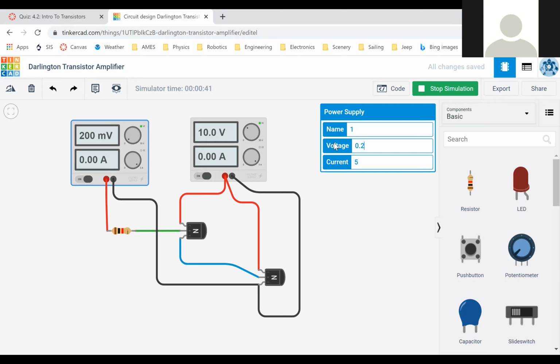And a diode has what we call a threshold voltage. And if you don't exceed that threshold voltage, nothing's going to happen. So 0.2 is less than the threshold voltage. 0.4, we're still less than the threshold voltage. 0.6, we're still not at the threshold voltage. 0.8, oh my goodness, still not quite at the threshold voltage in this case. So let's take it to 1 volt. And we should have reached it by now. That's 0.1. Oh, sorry. Okay, 1 volt.